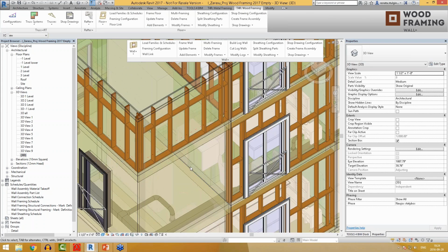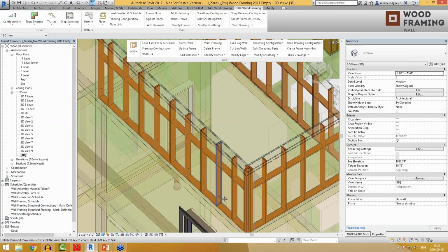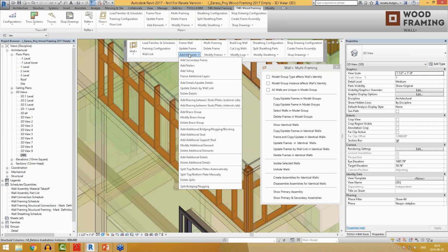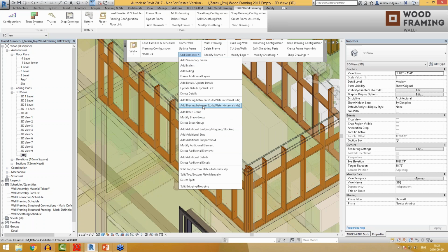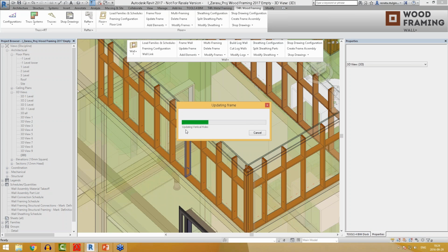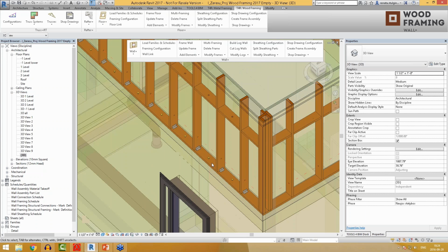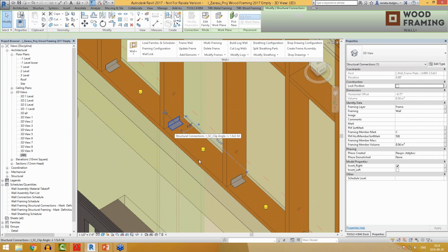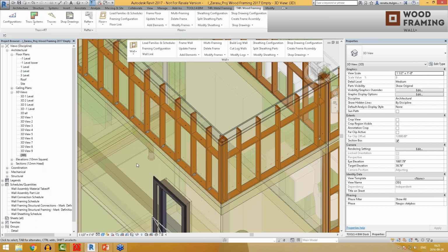And you can notice that in my case there are no details, like metal details or connections between the elements. It doesn't matter, anytime you can add them additionally. We have a function which can automatically add additional details. All these details are just sample connections and sample families in Revit, but you can modify them and create your own, and distribute them automatically in between the frames.